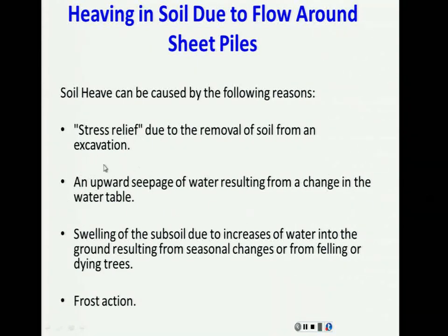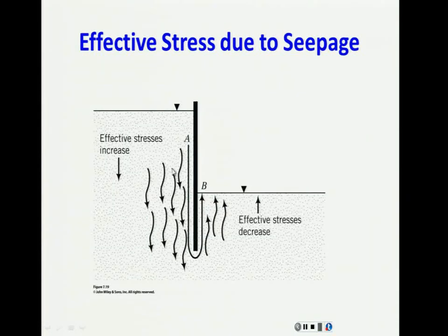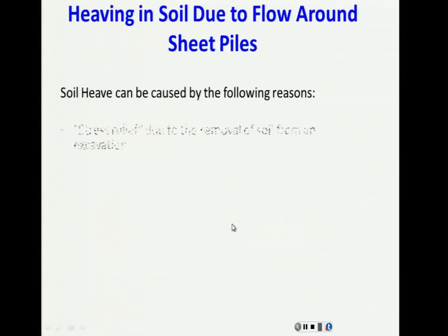Basically, the one that we are interested in right now is this one, because once again, when we are here, remember, this is going up, and this soil loses friction, to say it that way, this is going to collapse. This is going to basically come in this way, this is going to come in the other way, and the sheet pile is going to collapse. It's going to overturn in that part.